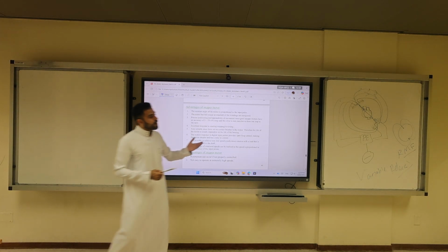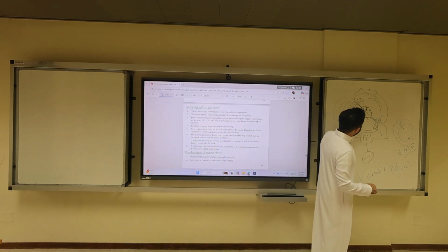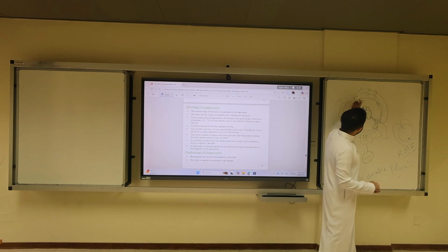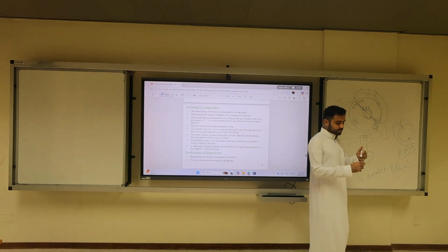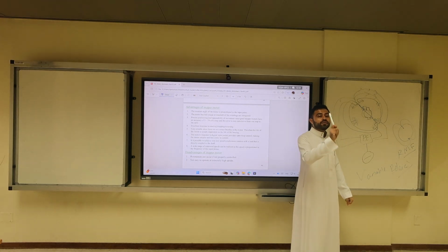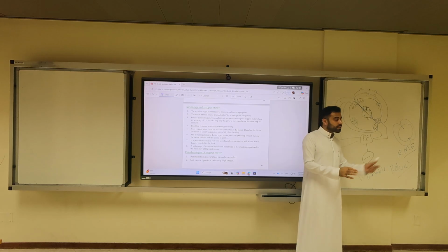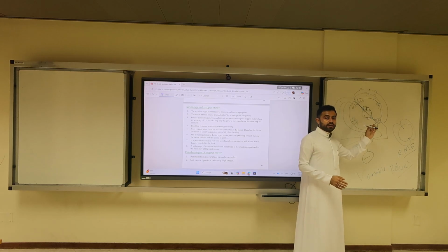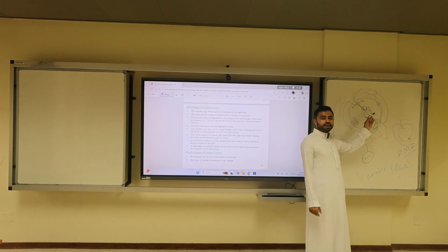So what will happen if I add coils here, and de-energize this and energize that, these two? What will happen? If it has enough inertia, that's the key, from the stop, maybe it will align, maybe not. We don't know. But assuming the rotor weight is negligible, it will definitely align here.